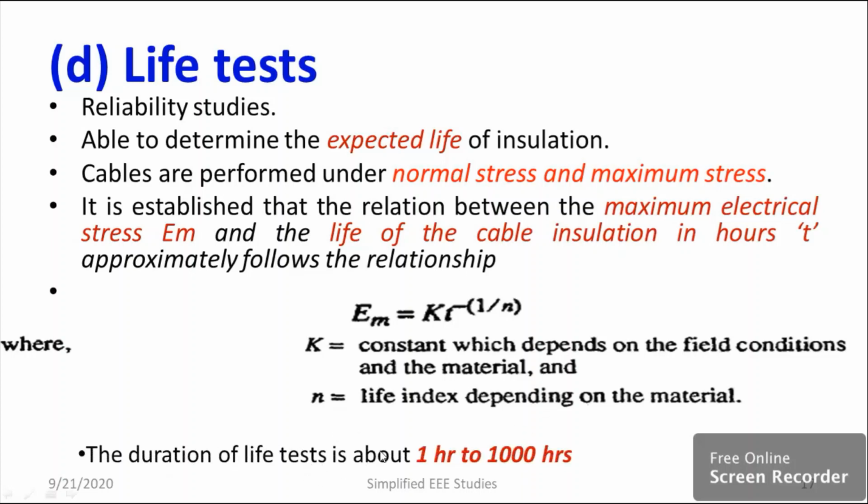The duration for conducting the test is 1 hour to 1000 hours. So from this we can predict how long the particular insulation can survive. From this you can calculate n, and you can verify how long the particular test piece can survive. Okay, that is very clear.